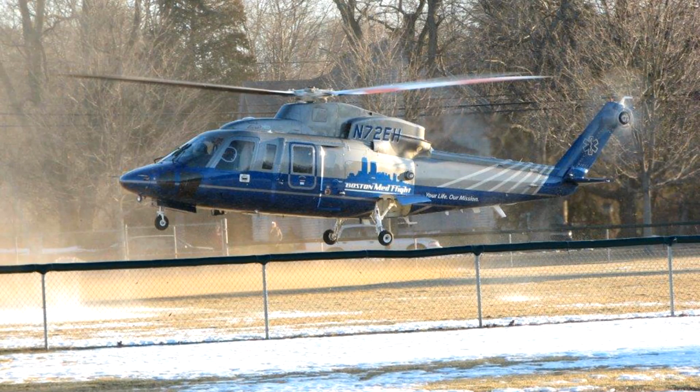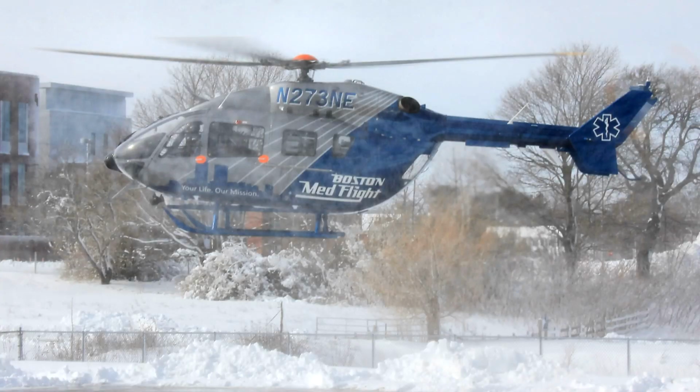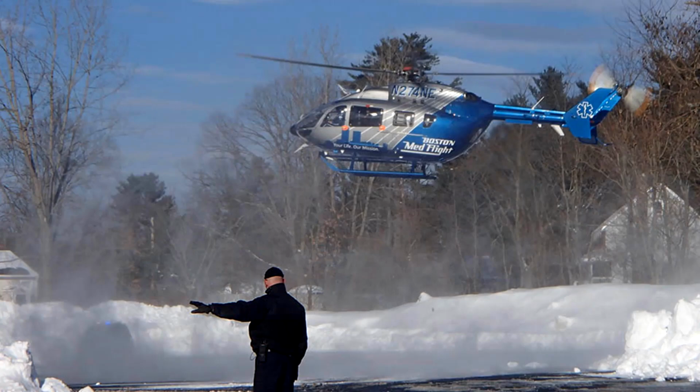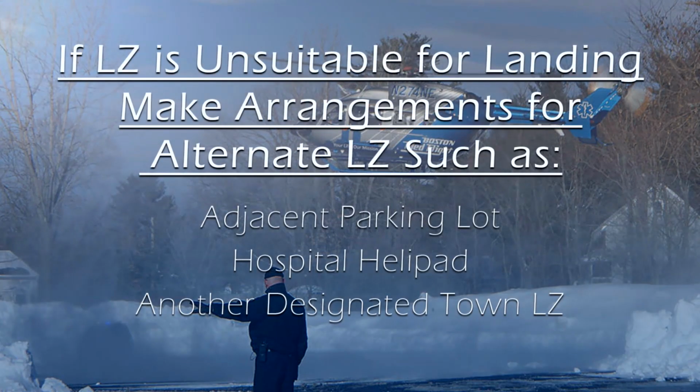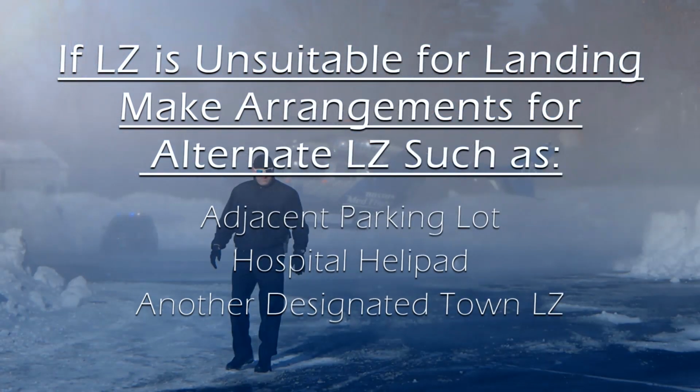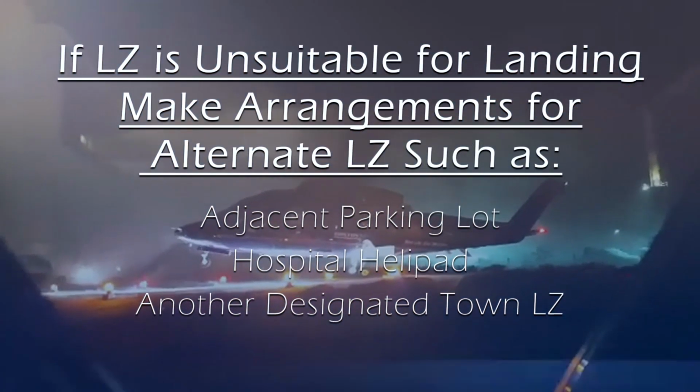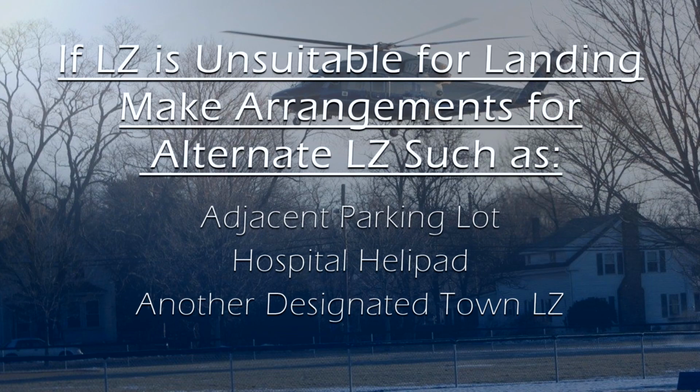The aircraft can land on firmly packed snow LZs. However, the aircraft will not land in deep snow. The LZ must be inspected to ensure the landing is possible. If the LZ is found to be unsuitable, make arrangements for an alternate LZ, such as an adjacent parking lot, hospital helipad, or other pre-designated town LZ.